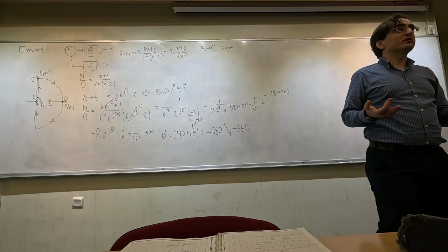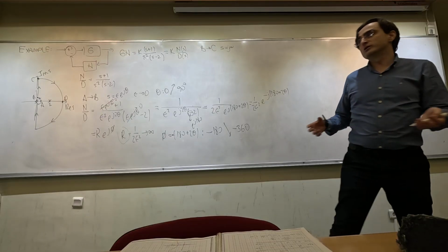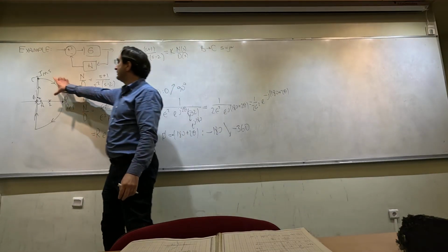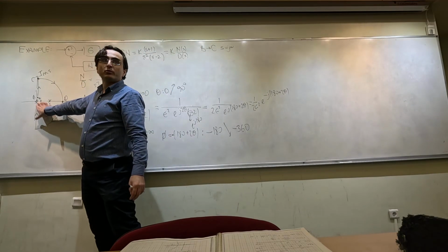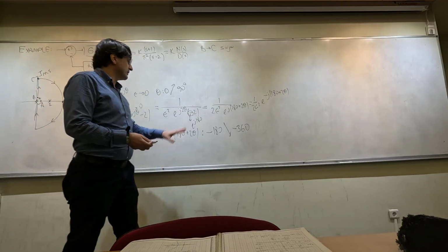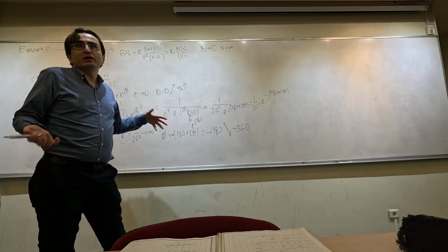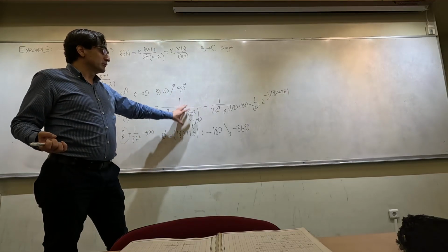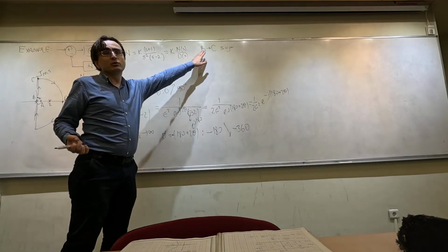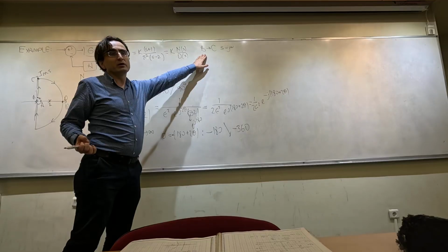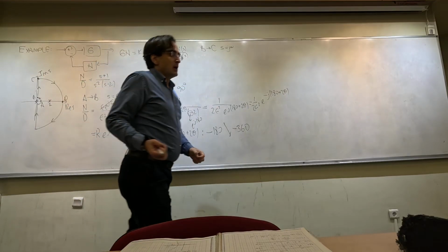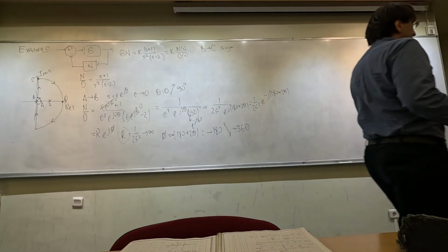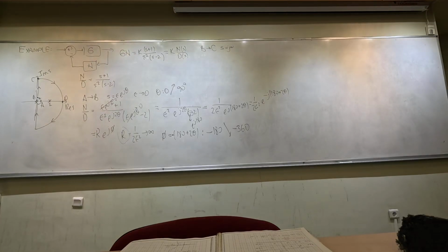This is the part actually given by MATLAB, for example. If you try to draw a Nyquist plot in MATLAB, you're only going to get the part from B to C, and you won't really get the parts at infinity. So in MATLAB, you will only get the part from B to C, and instead of drawing a Nyquist plot from B to C, we can try to draw the magnitude and phase of that quantity separately. And that becomes a Bode plot.